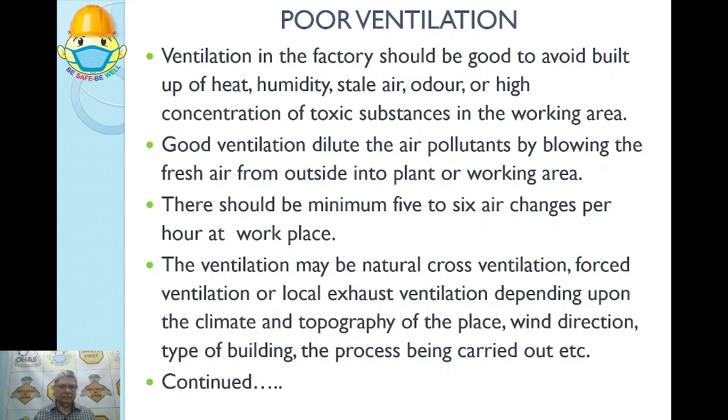Now how to do that? So there may be natural or cross ventilation. If you have the building in such a manner facing the wind, if there is a southwest wind, generally in our country you get the southwest wind. So if you have the building and position the building in such a way that the southwest wind comes inside, and if there are windows opposite to each other, there will be cross ventilation and sufficient air from outside will come.